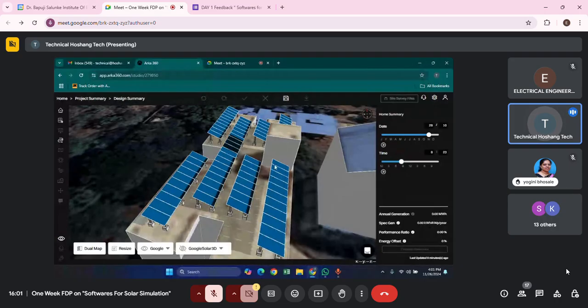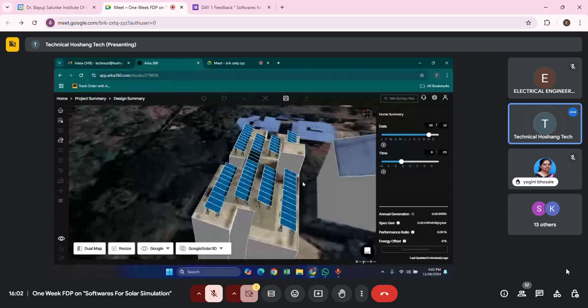See that the shadow from these solar panels is being cast on this structure. The solar height is not so defined, but this will be completely darkened. The total string being generated will have less power. So if a single panel in open sunlight generates let's say 9 amps of current, if a single cell is covered, it will drop up to 5 amps. So there will be a major difference of 4 amps, and 4 amps from a single panel or 3 panels will reflect into major losses in solar generation. So this is the disadvantage of using 335 watt panels.